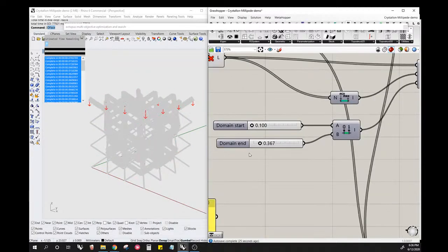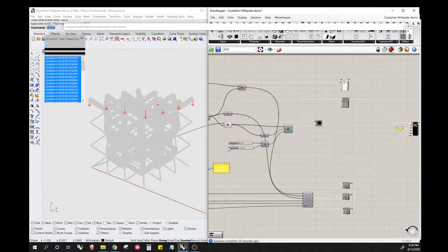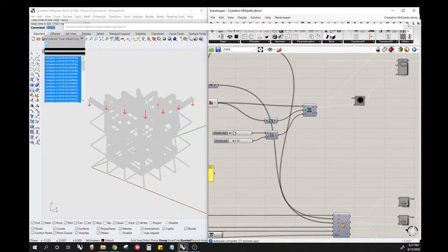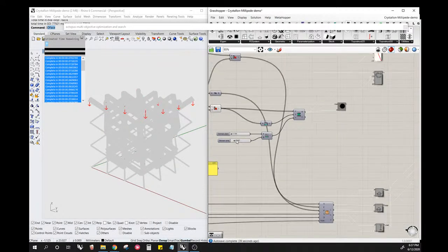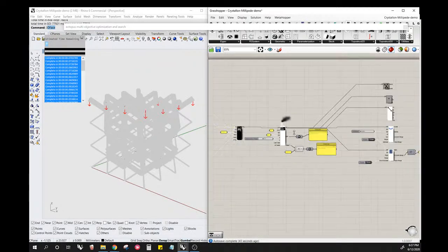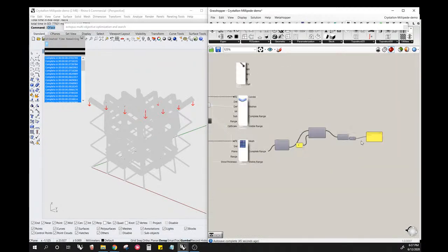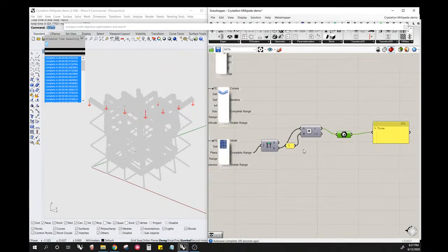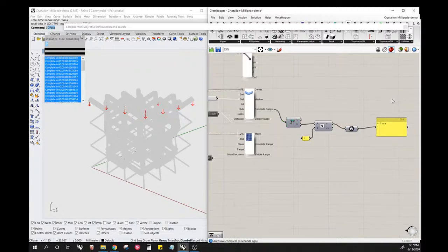And this, again, is where you could use Octopus to run these values, your thickness values, as parameters. And again, look for the least deflection and least weight. And you can also add a Boolean value as a goal. That's what I'll usually do here: I want to see if the yield strength is under 1. If it's true, it's a valid result. If it's false, Octopus will just ignore that result.